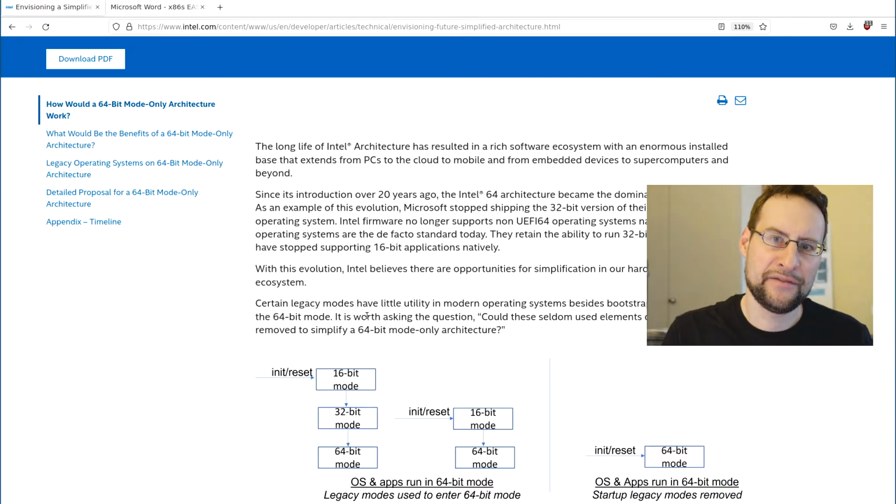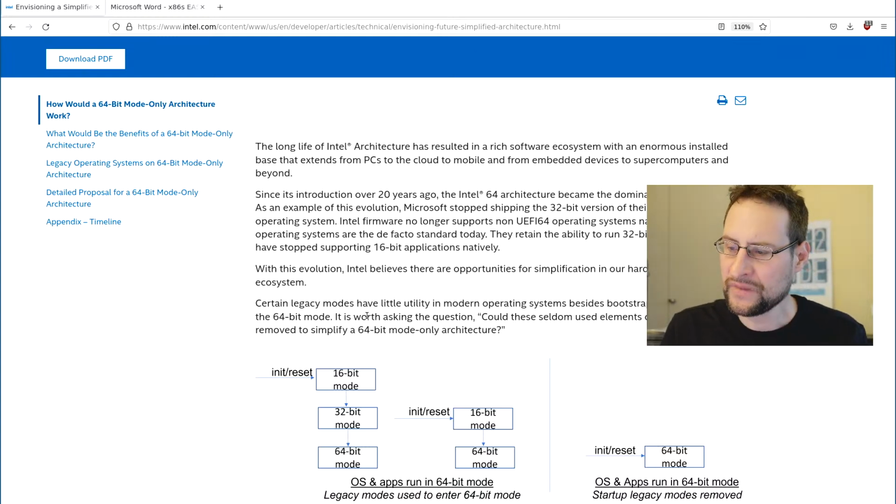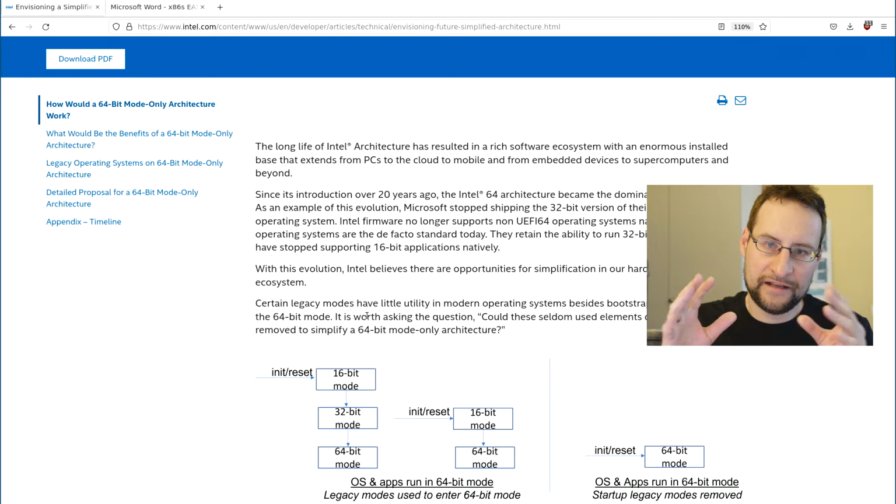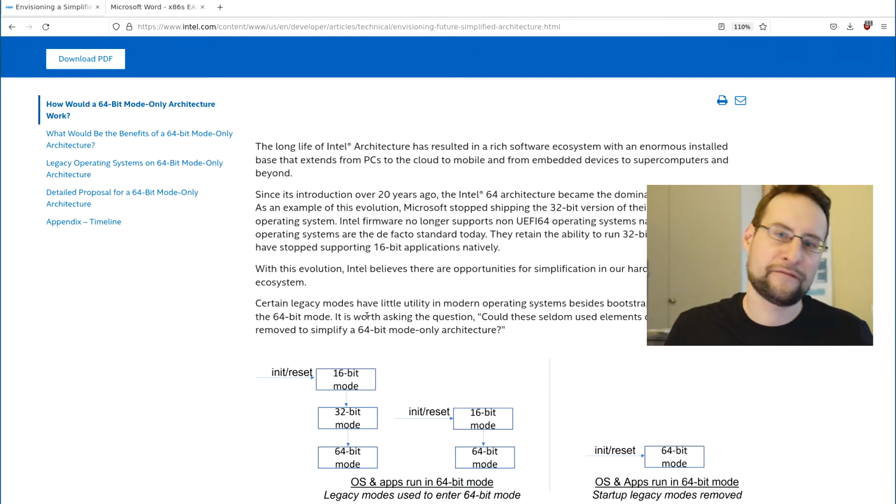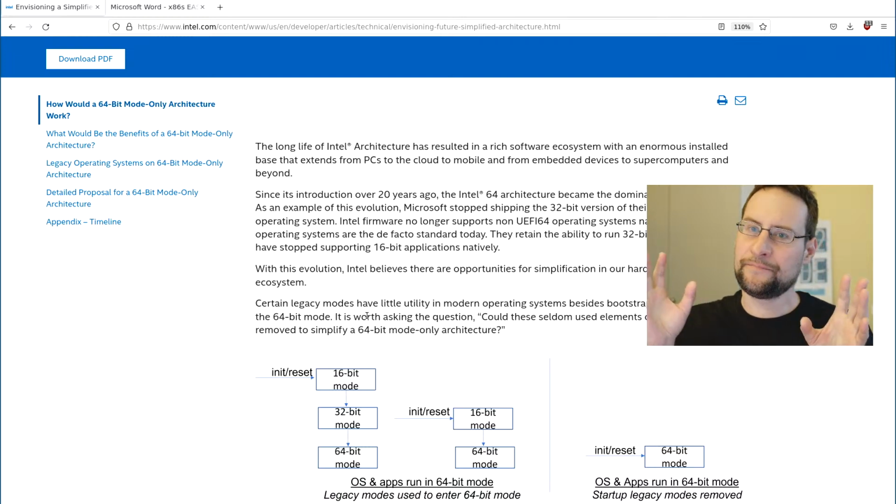And the Pentium Pro extended that with a physical address extension PAE to 36-bit, I believe, that you could not use at once because it still was a 32-bit processor, but at least similar to the 8086 segmented stuff, some database applications in user space could use other parts of your 36 bits of physical address extended memory. That is already convoluted enough, plus of course MMX and all the other architectural extensions,